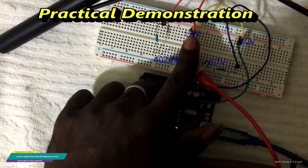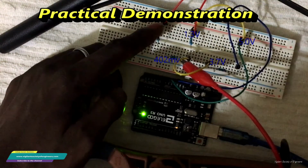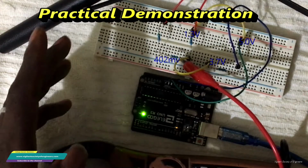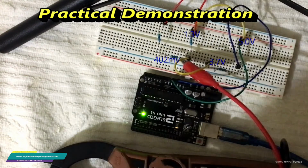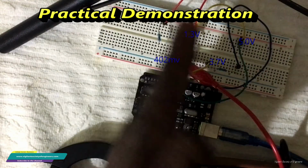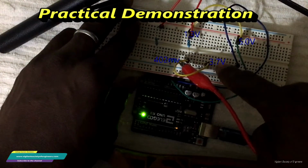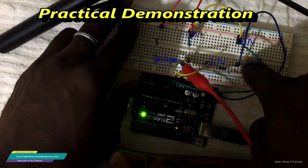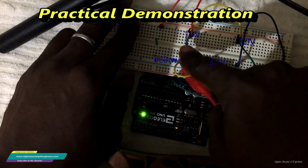All right, so now there's going to be a split between the voltage in series for the 100 ohms and the 220 ohms that is in series within the parallel side. So the voltage is going to split, right? Remember I said they add up, and it should add up to the differential of the voltage coming across from the voltage in this series circuit here, which is 3.7, and the supply side, which is 5, and that is what, 1.3, right?